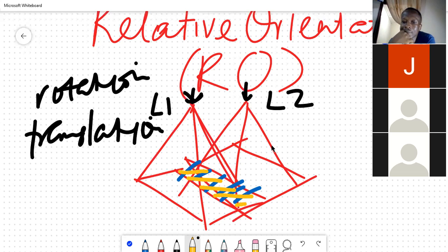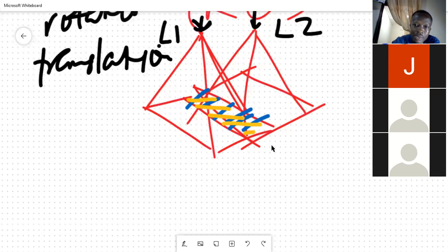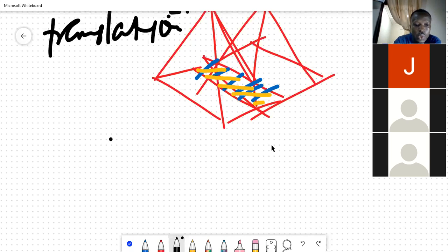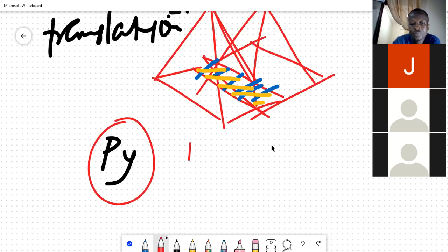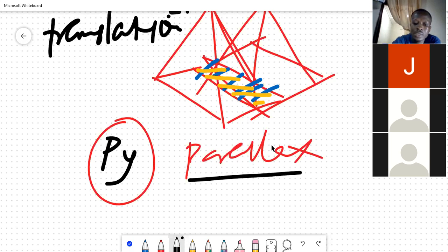So it's very important for us to know that this is not a trial and error, but a repetitive process, what we call the empirical process. So we check the values, we check for errors, test if there are errors. If there are no errors, then we move on. Now the errors that we are interested in relative orientation are the so-called parallax in the y direction. Remember that we've already talked about parallax, but the parallax that we refer to in this context is actually the bad one.